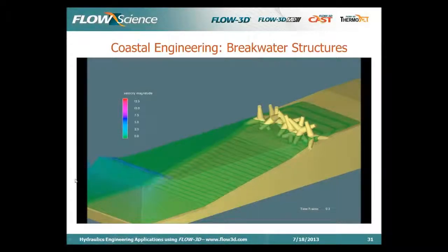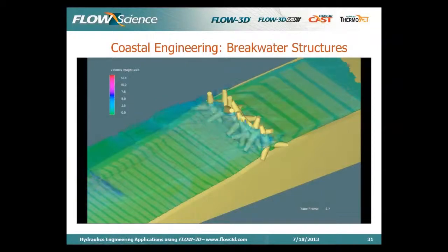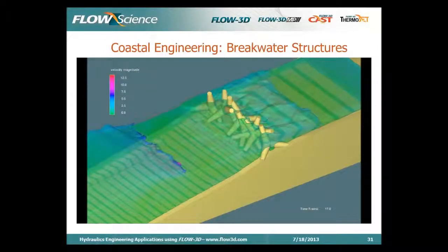Some coastal engineering. Breakwater structures, a common problem in coastal engineering, and if you look behind those tetrapods you can clearly see how the waves have been damped, and in terms of outputs, of course, you can measure all sorts of things before and after, turbulent kinetic energy and so on and so on. But you see how the three-dimensionality of the simulation works very well to get an accurate idea of what's happening behind the tetrapod.